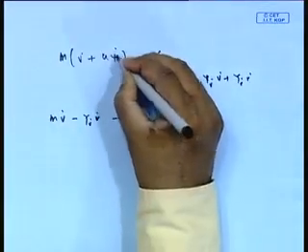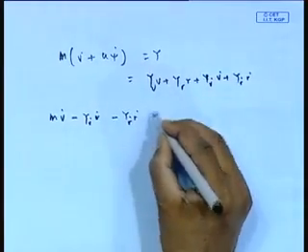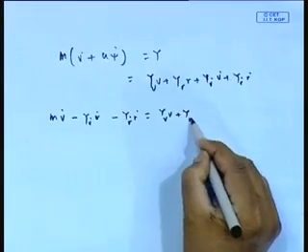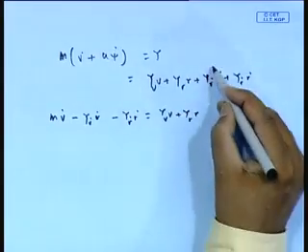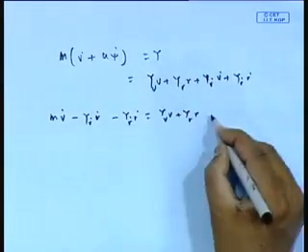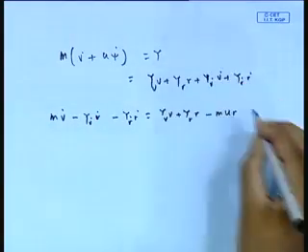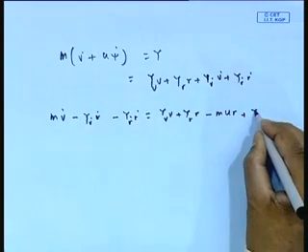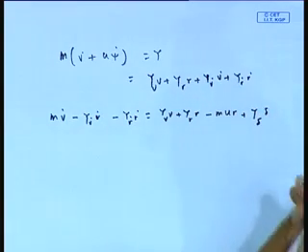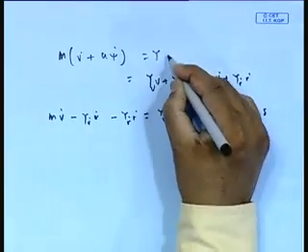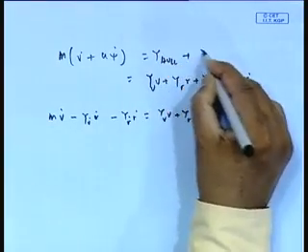equal to Y_v v plus Y_r r, minus m u r. See, this has been brought to this side, this to this side. Of course, I also have the rudder term, Y_delta delta, that is the rudder angle, plus the hull.